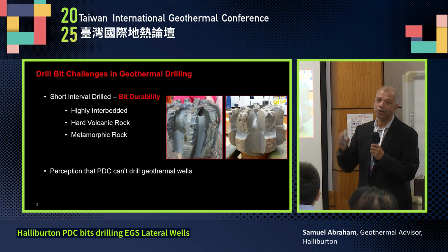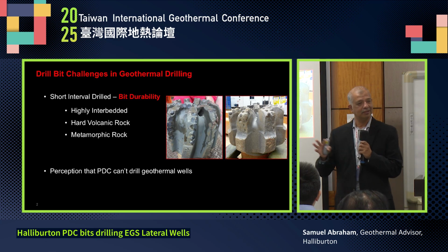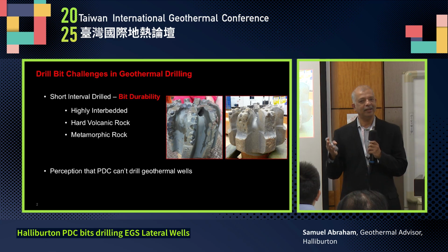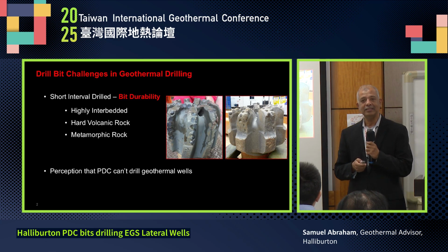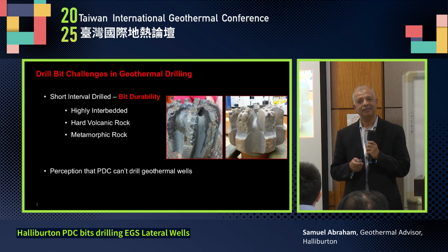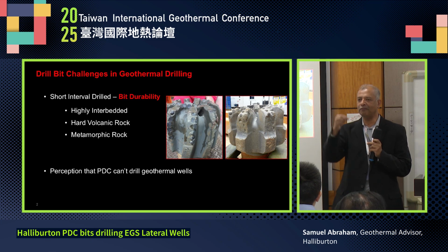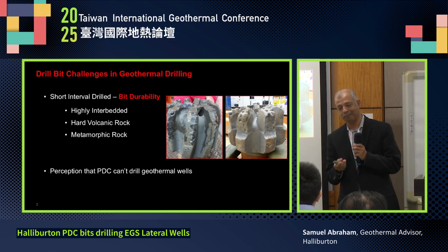But what I wanted to focus on today is that, yes, if the rock was very homogeneous, I would be talking a different story. But here, the rock is not homogeneous. It's an intercalation of formations. So here, selecting a bit to match a formation is a challenge. Plus, keep in mind, your bit selection is quite important because before your bit actually touches the ground, the fluid flowing through the formation starts to make an impact on the formation. So here comes your hydraulics, bit hydraulics also.